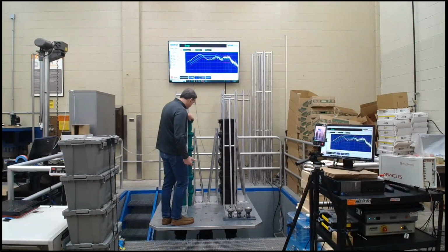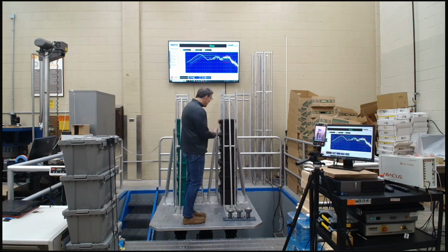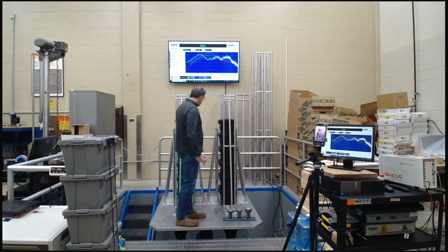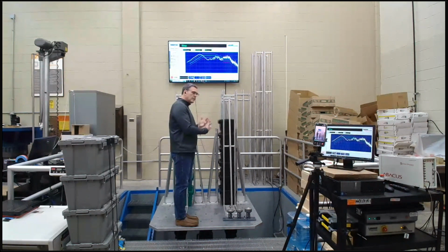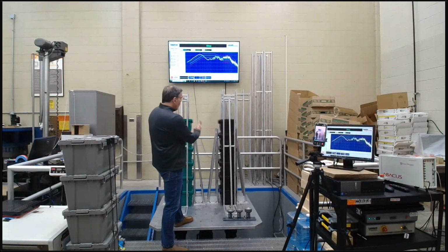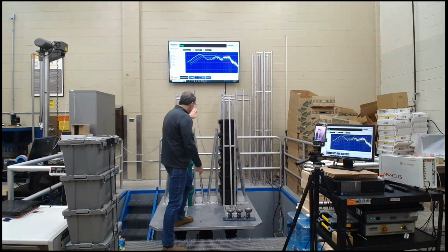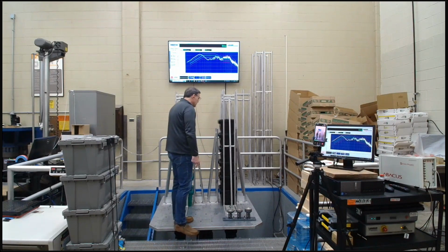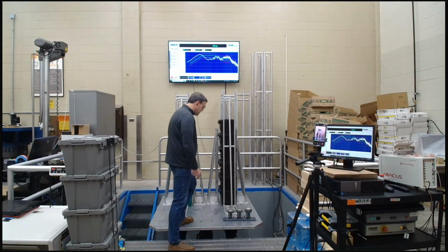They're not filled. So there's a stack of 6 of these containers. They're not full. They're lighter as compared to these black ones. Same size, same number, heavier, lighter. The idea there is to show, when we do some of this testing, the difference in what we would call column stack resonance based upon the weight of those loads. One will have a certain resonant characteristic as compared to the other one. Lighter loads would be a higher natural frequency, heavier loads should be a lower natural frequency.